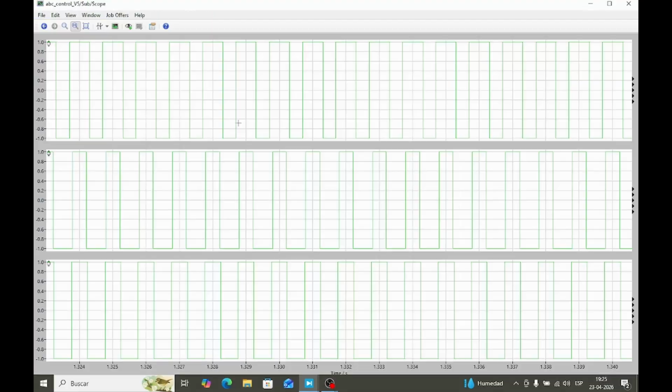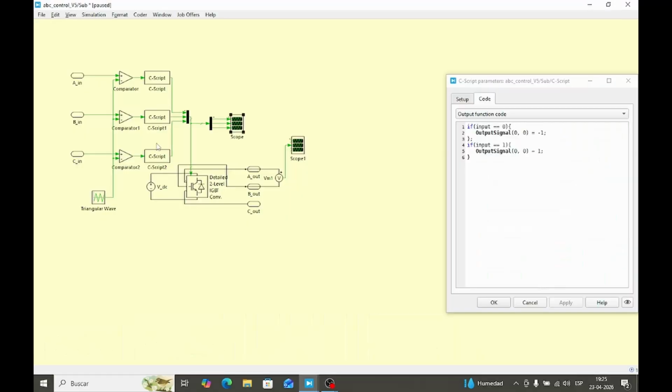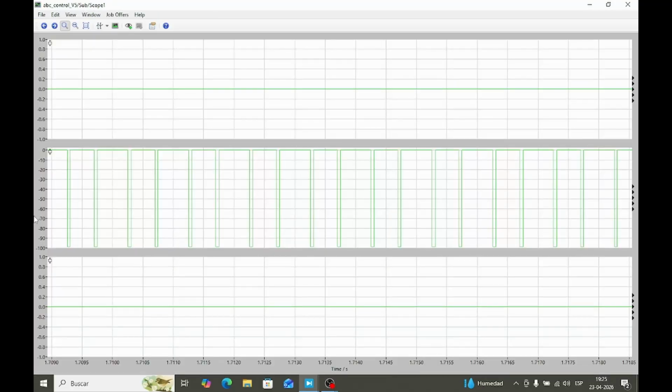We can see the information for each phase and the control signals, these orders for the inverter, and they are rectangular waves as we could expect, oscillating from 1 to -1, and so on. This inverter is supplied with DC voltage, and at the output we will receive the control signals that are sent to our permanent magnet synchronous motor. I placed here a voltmeter just to see what we are getting from the inverter. As we can see, here are rectangular